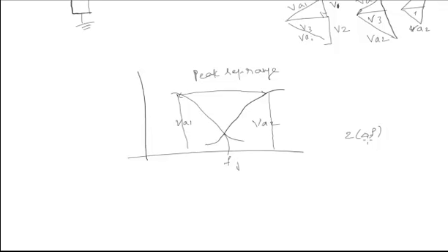And here, a disadvantage is that any variation in amplitude of the input due to noise modifies the discriminator output. So undesired frequency components corresponding to amplitude variations are produced in the detector output and the output gets distorted. In order to prevent the distorted output, we can use a limiter circuit. But due to the use of a limiter circuit, the arrangement might be complex. So in order to overcome this difficulty, we are now going to discuss the next method, which is most widely used.